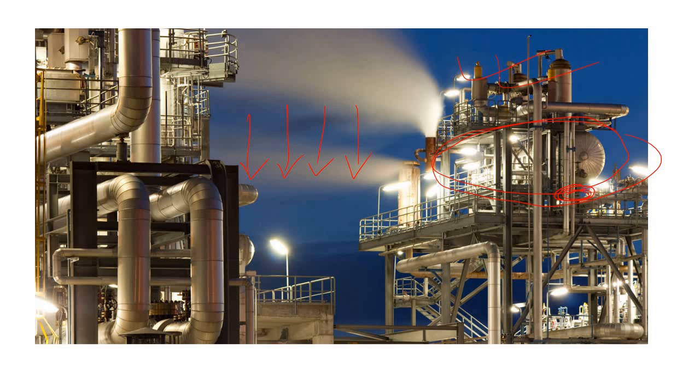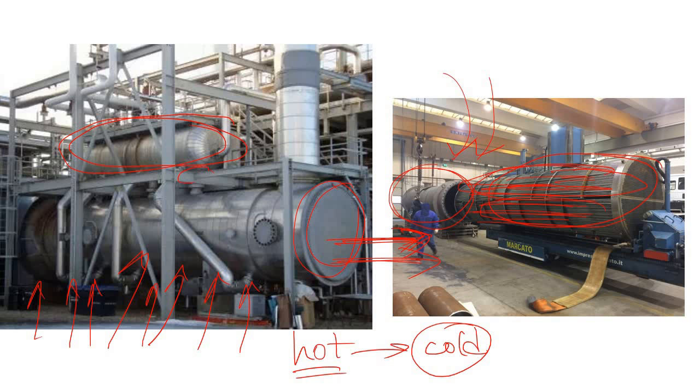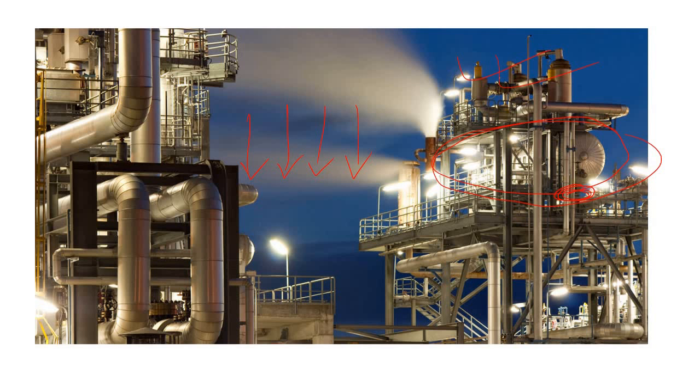Go back to the previous slide. Here you can see that they are anchored here and here, and you have some pipe that is coming from here and then going into this exchanger. So due to this piping you will also have some anchor load and pipe friction load. You can visualize this vertical load and some amount of lateral load due to the pipe friction. This pipe friction load or anchor load is very negligible for an exchanger.